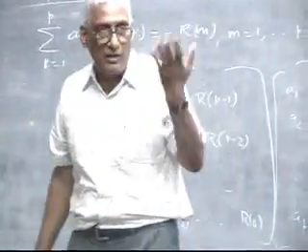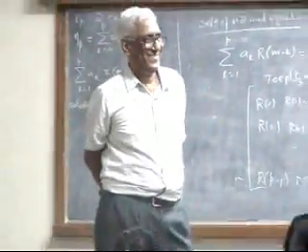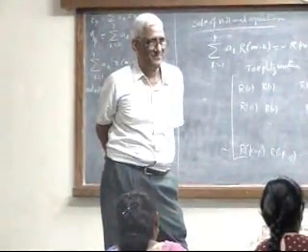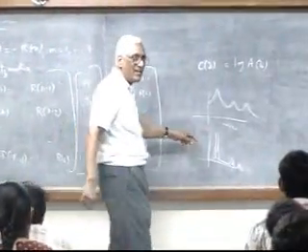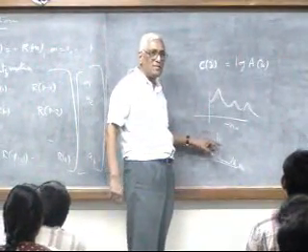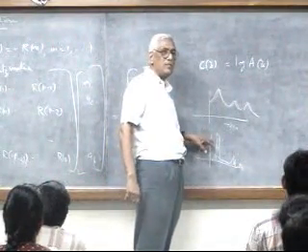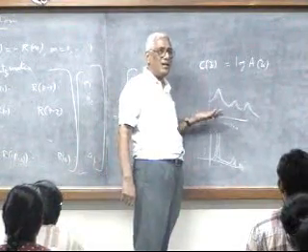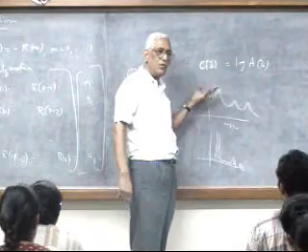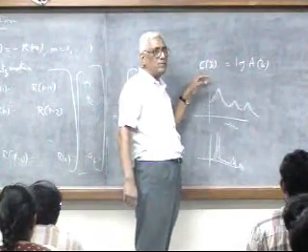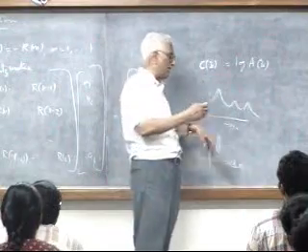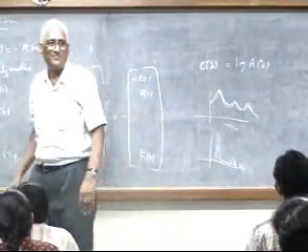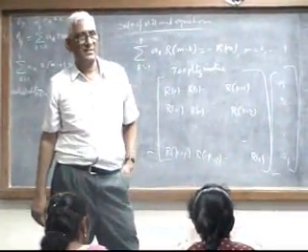Now you try to find the Euclidean distance between these two, to find out how close they are, and you are in big trouble. Why? Because the distance is very large here. This minus this gives a large distance, unless this coincides with this. So with any approximate match, you cannot have a good distance measure. On the other hand, if you take the log, you are slightly better. If you go to the cepstrum and then smooth it, that means truncate it and come back, then you will get both of them something like this. Then there is a good match, because it blunts some sharp peaks.